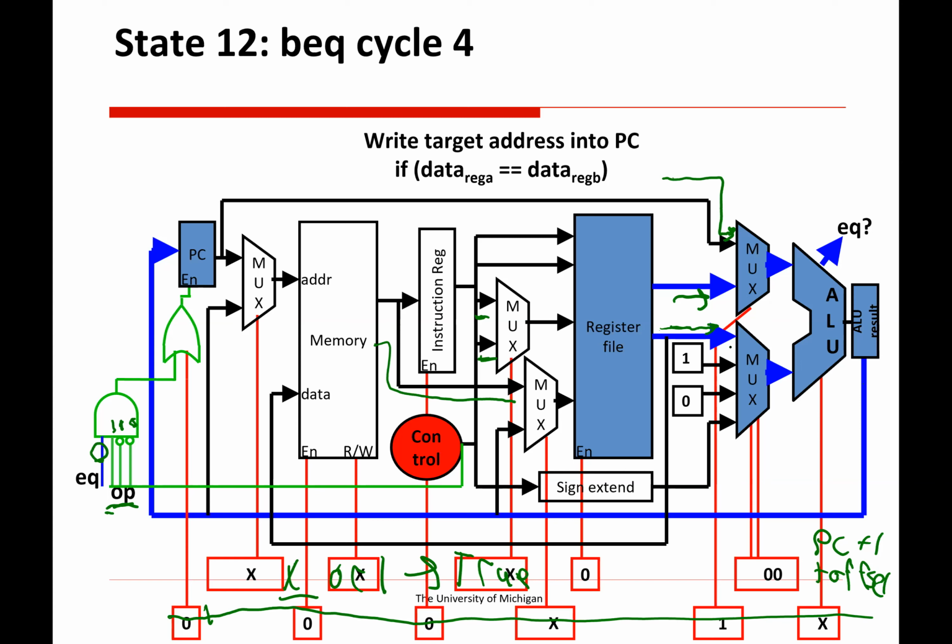This one is if it's register B. This is if we're doing PC plus 1. 0, we didn't really talk about, but we can get to that later. And then the bottom one is if we're adding something with the offset, which is what would happen with load or store words, because we're adding a register value to an offset.